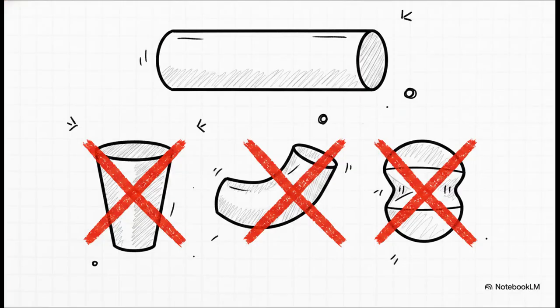The big takeaway here is that Total Runout is a composite control. By evaluating the entire length of the feature at once, you're getting an incredible amount of control from just a single callout on your print. If the machinist makes a part with too much taper, it fails Total Runout. If the axis isn't straight, it fails. What if it's perfectly straight but slightly out of round? Fails again. It's guaranteeing overall surface consistency across the board.